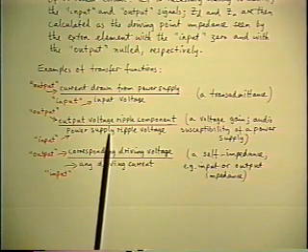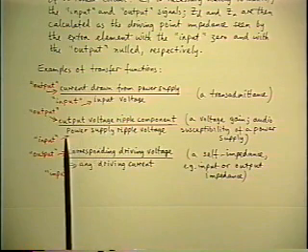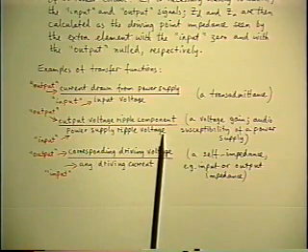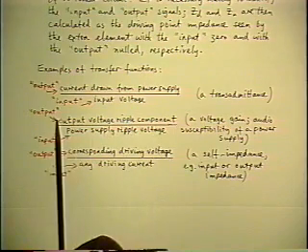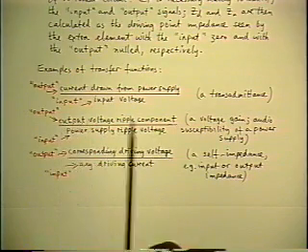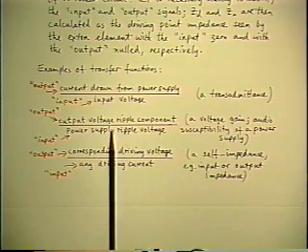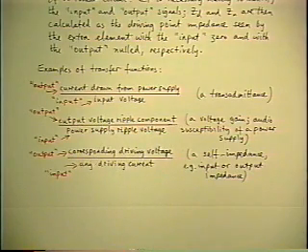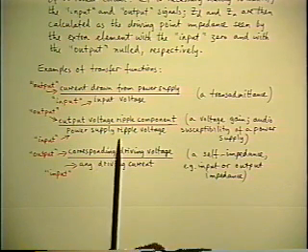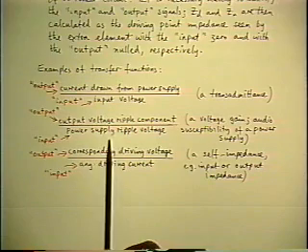So there is another transfer function that says, considering the power supply ripple voltage as another independent input, how much output voltage ripple you're going to get resulting from that. That is another transfer function that has to meet a specification. That's a voltage over a voltage again, so in a sense it's a voltage gain.